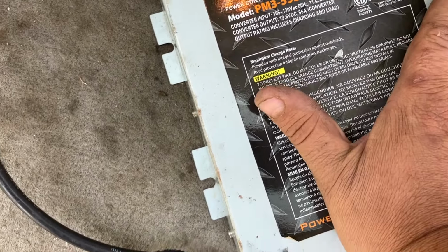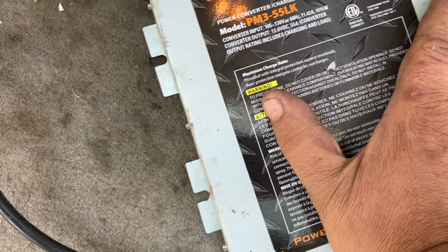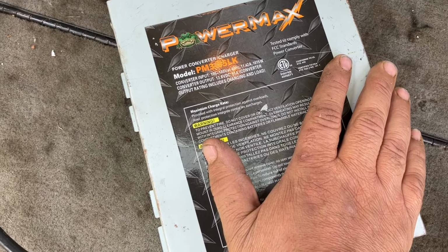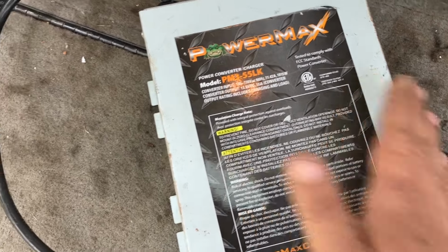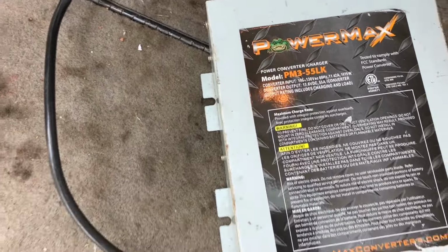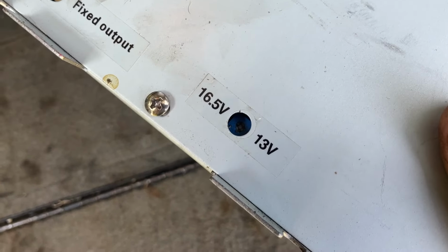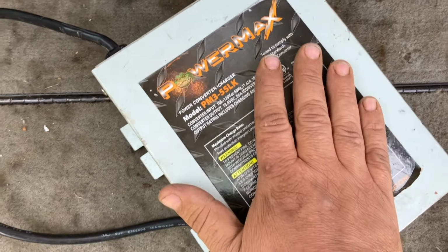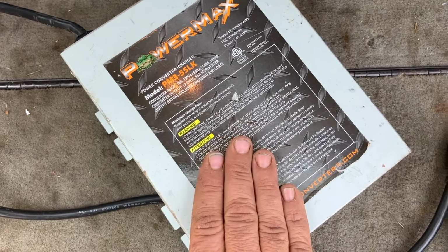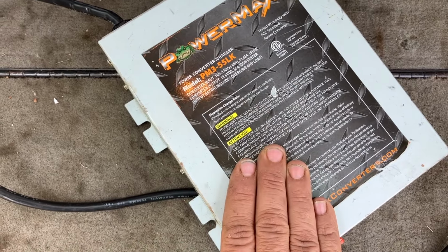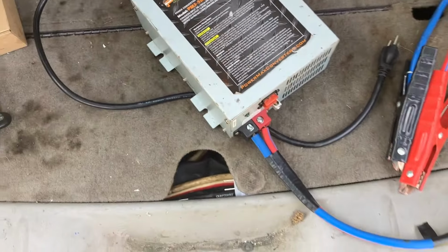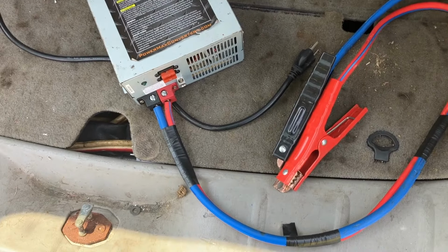They actually design these a lot of times to work with RVs that want to power their 12 volts off of AC or something, but this one is adjustable. So you can adjust it from 13 to 16.5. I usually keep it at about 13.8 for GM. On Fords, I've had them come back when you're programming and say, sorry, the battery voltage is too low. I crank that up to 14.2 and then it'll program them. So Fords can be a little flaky about their battery voltage.